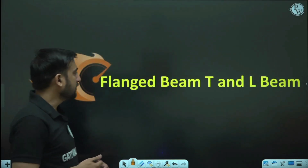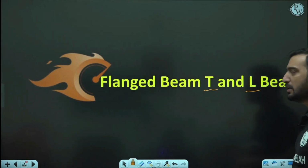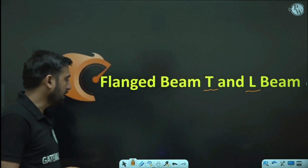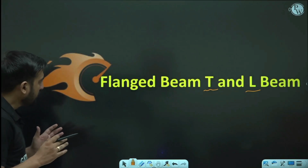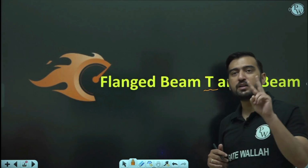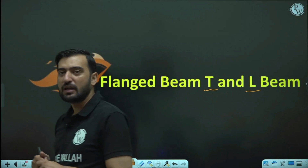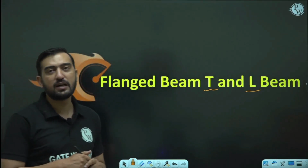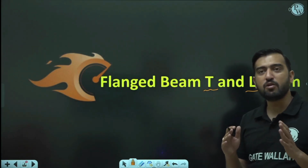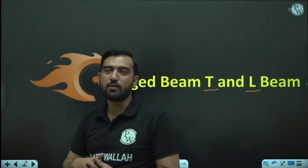My dear friends, flanged beam, as I told you, here we are going to cover T section as well as L section, T beam as well as L beam. The very first step is that T and L beams, the flanged beams, can be divided into 2 parts. One is the isolated condition and the other is the monolithically casted condition. Isolated condition is that condition where the entire T beam or L beam is casted at once. After that we are going to put the slab over there.